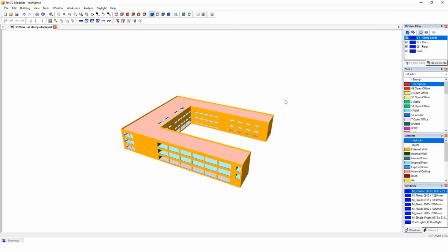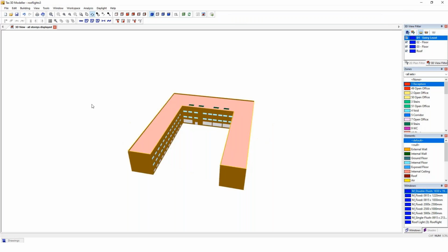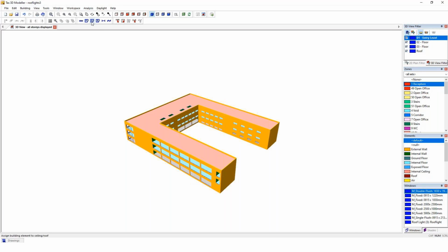The next step we can do is create the analytical model, but first I want to use our set zone option to basically highlight zones in the model and see if I can find just the zone that maybe not new, but has actually changed in the merge process too. So as I select zones in this list, you'll see them highlighted in the geometry. And if I get to one in particular, there's a few here that have actually been extended.